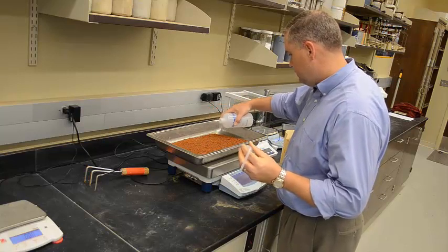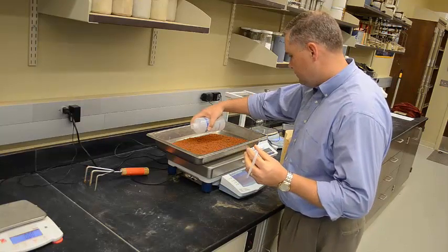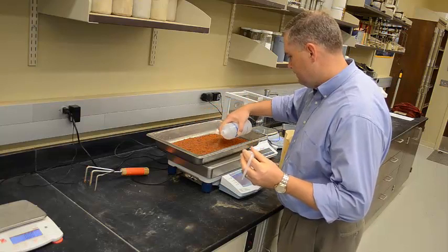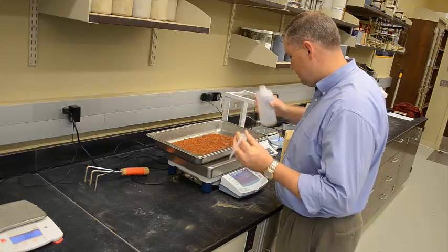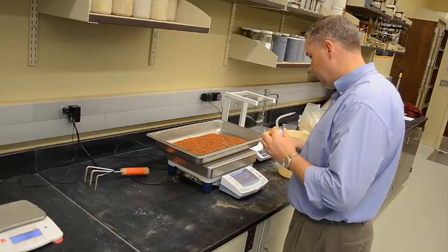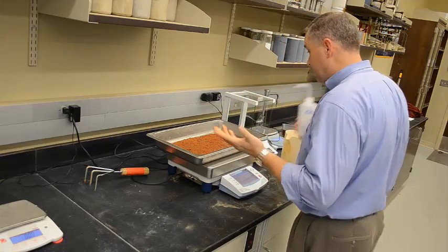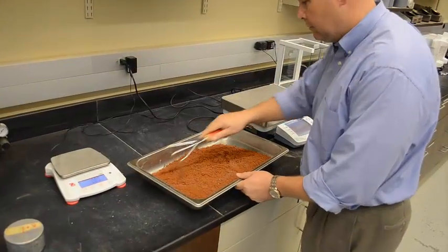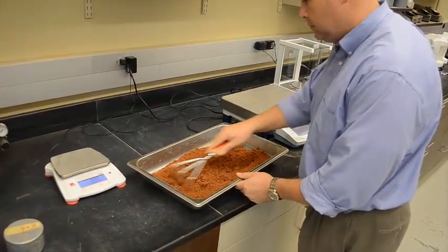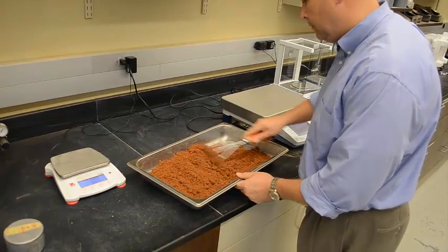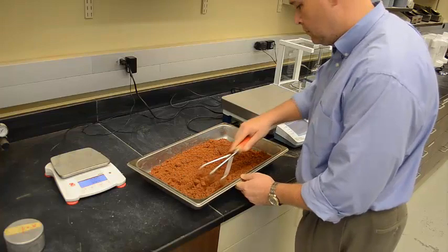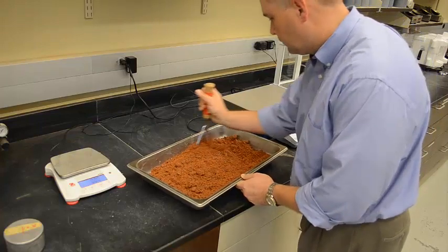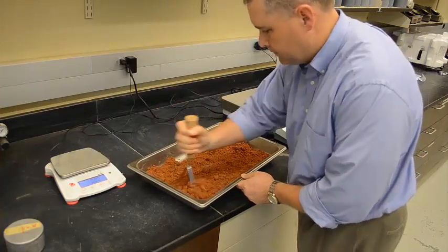Again, you want to add the moisture in a fashion to where the moisture doesn't go onto the pan, it goes into the soil particles, because you need to mix it and have a thorough, consistent moisture content throughout the entire sample. Again, we're mixing it to be consistent, so where there's no dry areas in the corners or wet clumps in the centers. And that's where you just get your hands dirty and go at it, which I'm not doing yet, which I should.